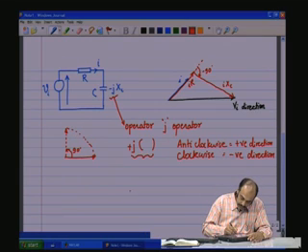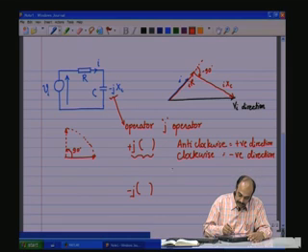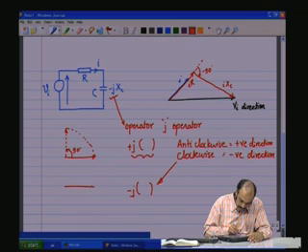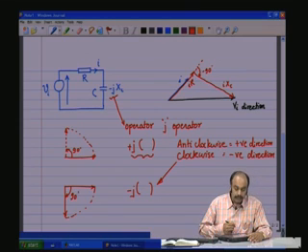Now, if you had minus j into something, then that is going to result in negative direction, which is clockwise. So, if I had the same vector in this form and on this you operate on minus j, that is going to rotate minus 90 degrees clockwise to obtain this new position.